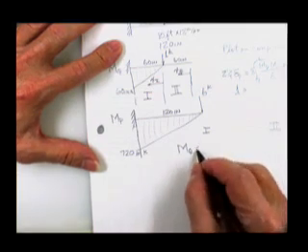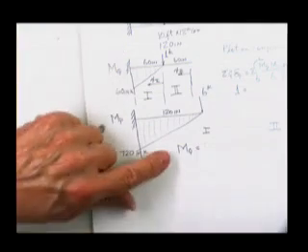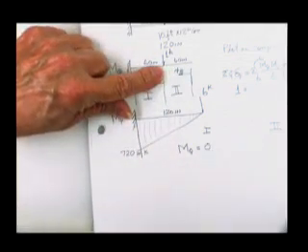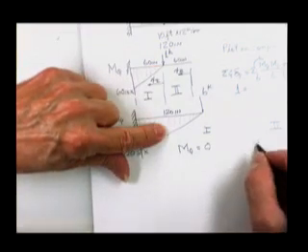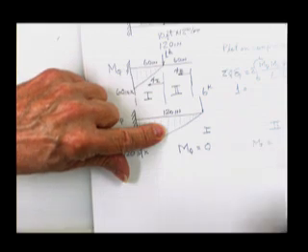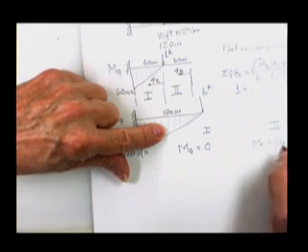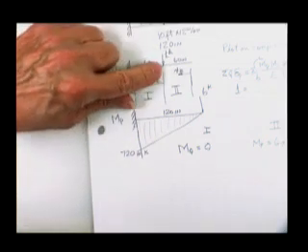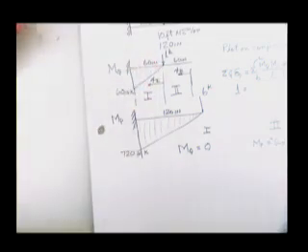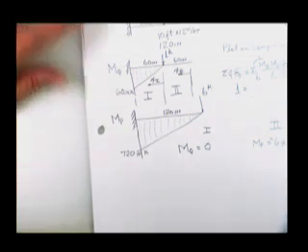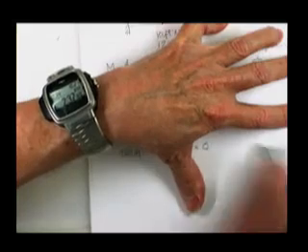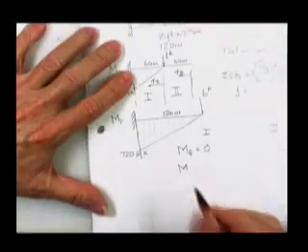M sub q is equal to, due to the Q loads, there is no moment. And due to the real loads, 6 times x. I don't know, it's up to you. You might really say it's a minus 6x, and probably ought to if it's a negative moment in that region. Whoops. Excuse me. In region 1.